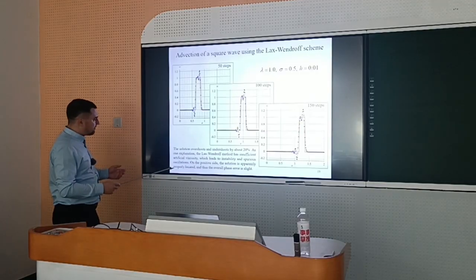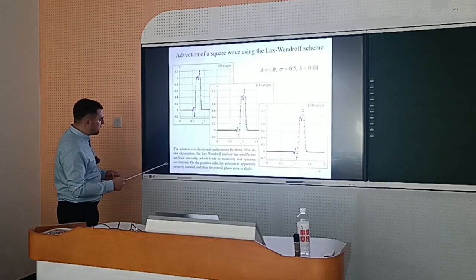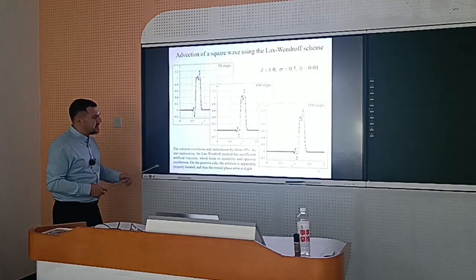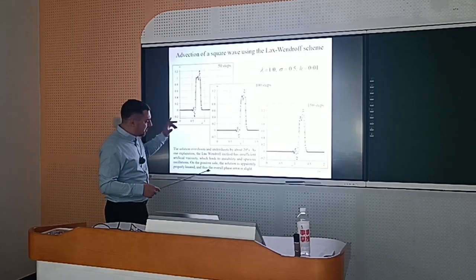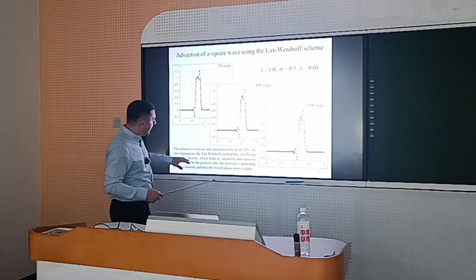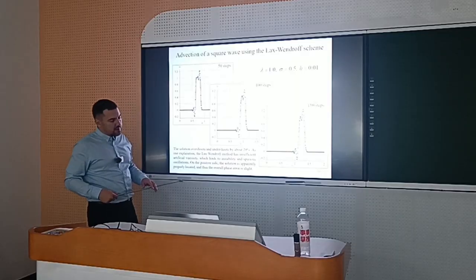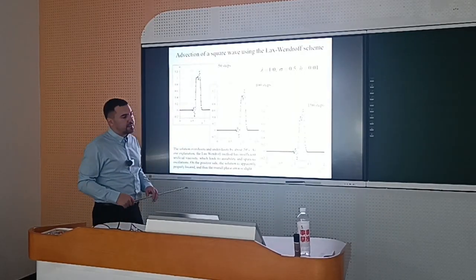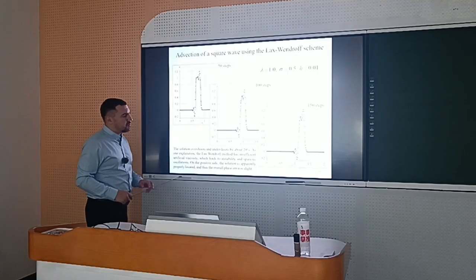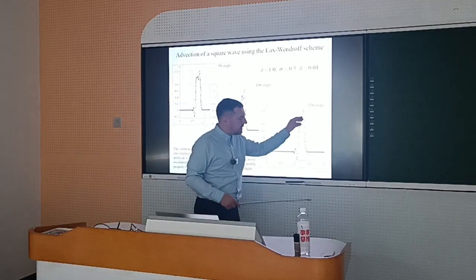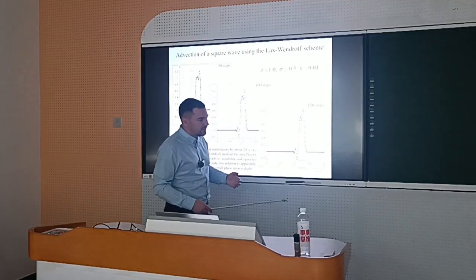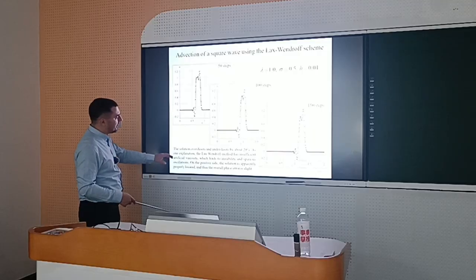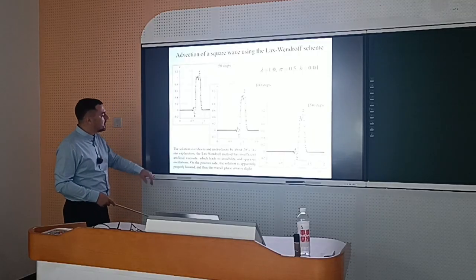As one explanation, the Lax-Wendroff method has insufficient artificial viscosity, which leads to instability and spurious oscillations. We do not discuss the artificial viscosity here, but when people first tried to carry out shock capture simulations in the 1950s, the idea was how to compute the shock wave. We should add numerical viscosity to our envisaged model. That is why this result can be interpreted as the Lax-Wendroff method having insufficient artificial viscosity.